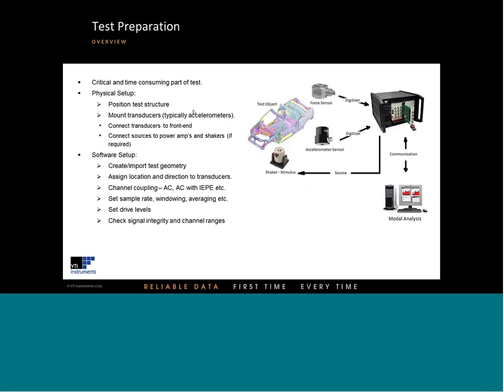And then the software setup, which is obviously what we'll focus on, since at the moment we're talking about software. Import the test geometry, assign location and direction to transducers, channel coupling, whether that's AC or AC with power to transducers, sample rates, windowing, averaging, drive levels, and so on.